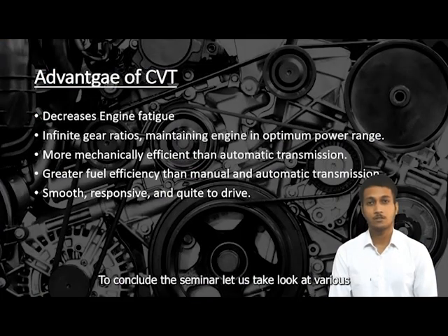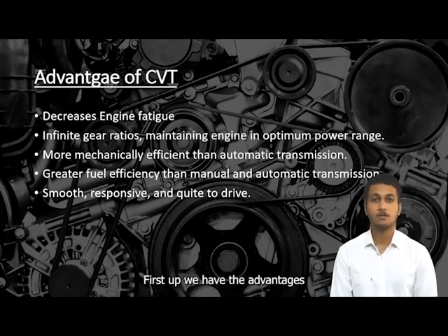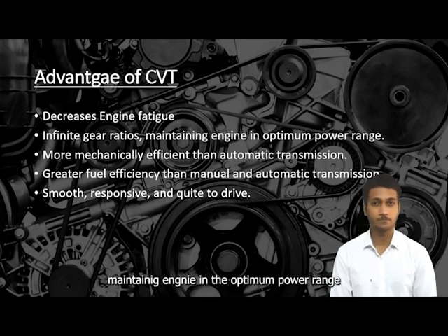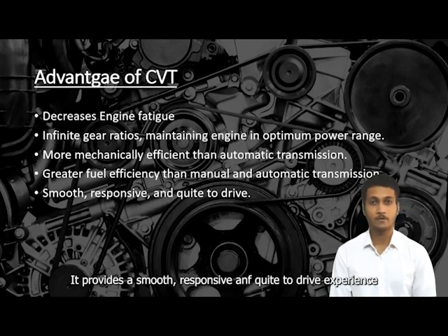To conclude this seminar, let us take a look at the various disadvantages and advantages which CVT provides over the conventional transmission methods. First up, we have the advantages: it decreases the engine fatigue. It provides infinite gear ratios, maintaining the engine in its optimum power range. It is more mechanically efficient than automatic transmission. It provides greater fuel efficiency than manual and automatic transmission. It provides a smooth, responsive and quiet driving experience.